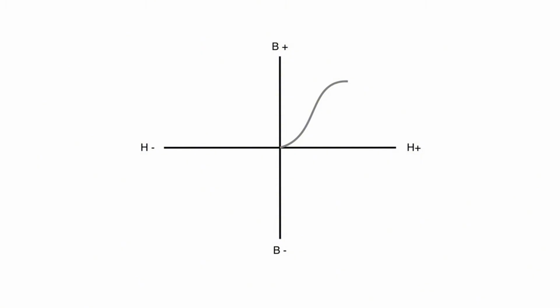So what's happened here is, if you can see, as we increase our magnetizing force in, say, some sort of iron core or steel core, it could be any kind of metal, then you're going to see that the flux lines increase. So again, we're talking about a wire wrapped around a core, so we're basically creating an electromagnet. As we increase our magnetizing force, our flux lines increase until they get to a certain point.